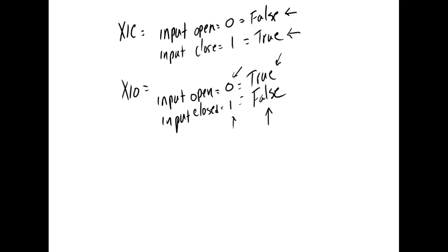Every input instruction you put in a PLC is defaulted to examine closed. So you can't say an e-stop button. An e-stop button is nothing but a normally closed push button that latches. So an e-stop button latches when you hit it, and you deliberately have to do what? Most of them, you have to twist it and pull it out. So when you hit it, you break the circuit, and then you twist it and pull it back out. So e-stop buttons cannot be momentary contact push buttons. They are literally supposed to lock.